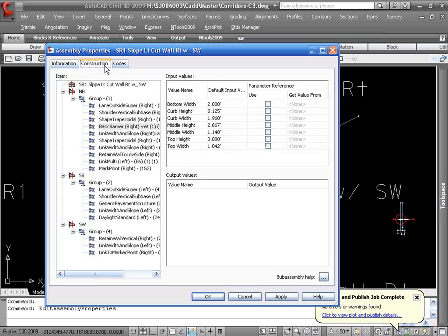So each offset has its own group by definition. You can't stick them together. But when you copy it and start creating new bunches that come with it, it may create new groups. And if they're not in a sensible order, like if you have something going from pavement that's in one group to a shoulder that's in another to a cut fill that's in the first group, the cut fill line gets all screwed up because it tries to build it before the shoulder has already been done.